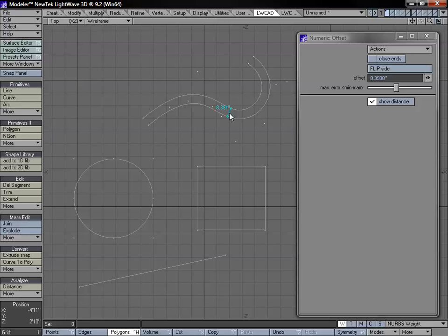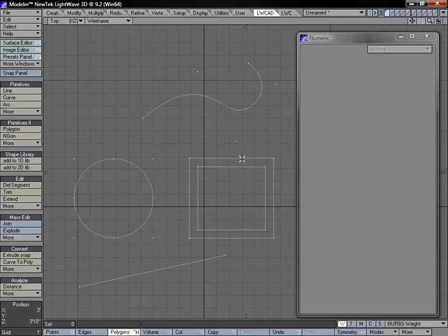Also note, if we take a look at our curve and our line, which are not typically closed end, they're just individual lines, we can see our offset creates open-end points. So that's one thing to keep in mind. We'll just go ahead and we can edit that if we want. And if we go beyond our values, we can end up with some rather interesting looking curves. So you want to make sure that you're not going beyond a certain value. Go ahead and hit the spacebar just to clear out that tool.